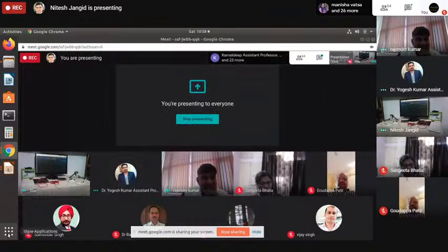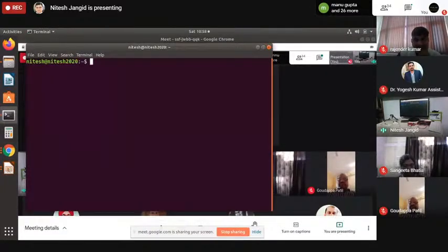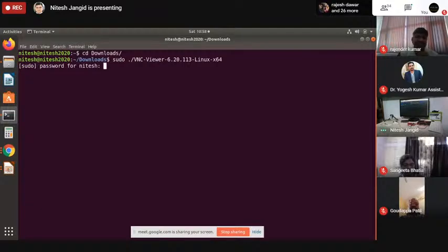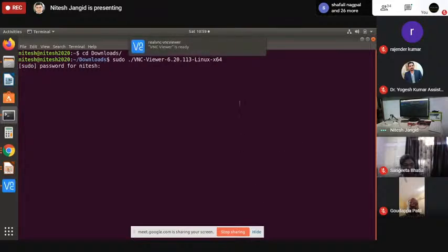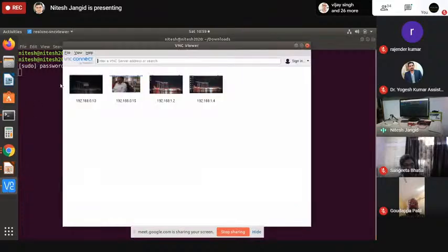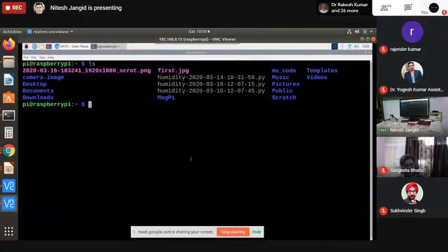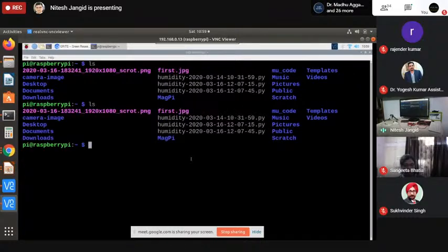Yes, sir. Okay. So please see carefully what I'm doing. I'm just launching the VNC viewer. So I just launched it, and since the IP of my Raspberry Pi is this, I just double click it. So now we can see that remotely I am accessing the Raspberry Pi here in the video. If you can see, fine. So I am handling this Raspberry Pi from my machine.